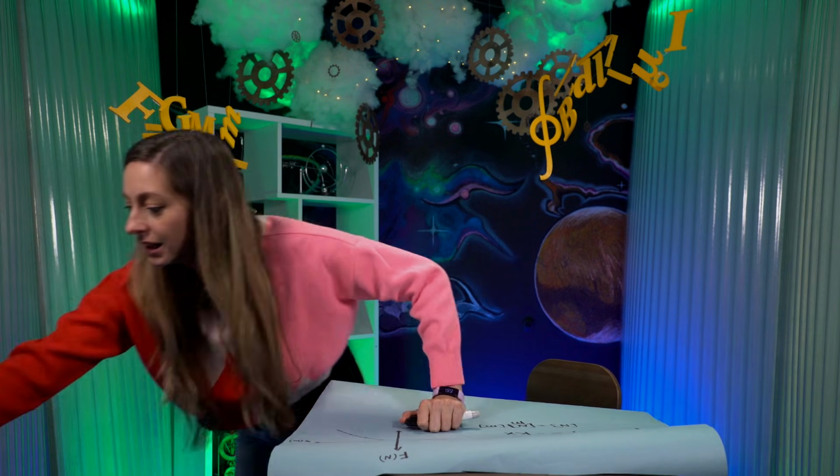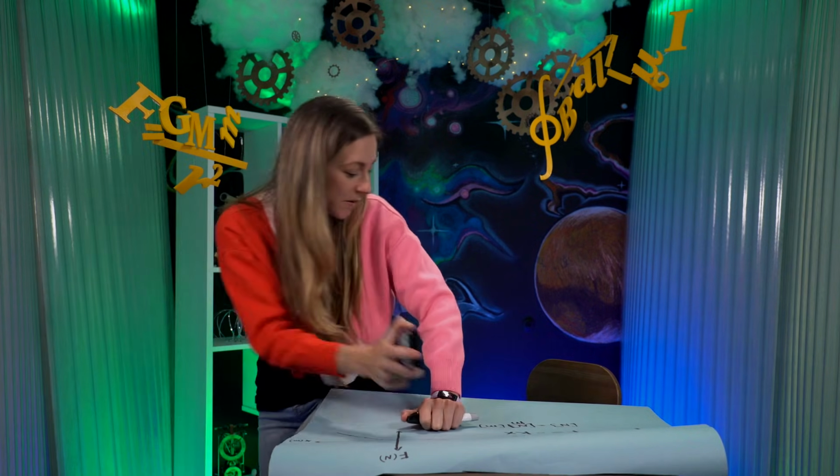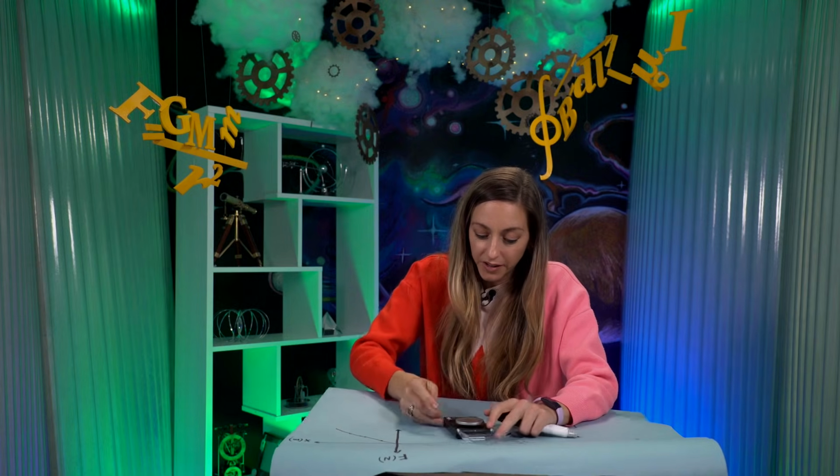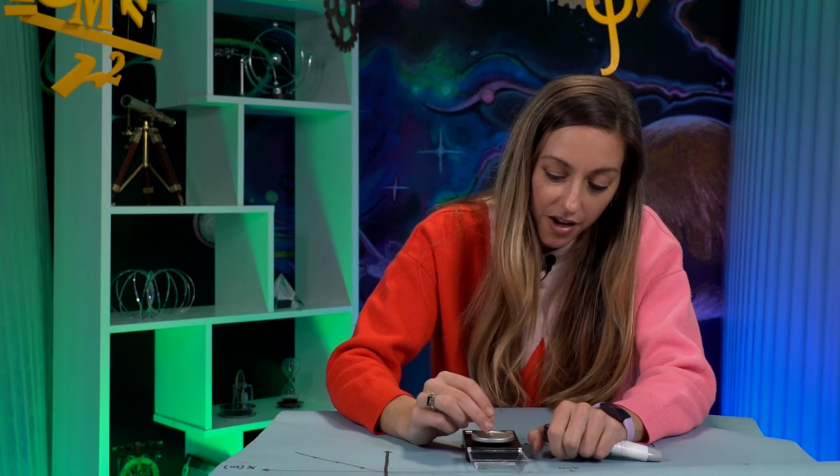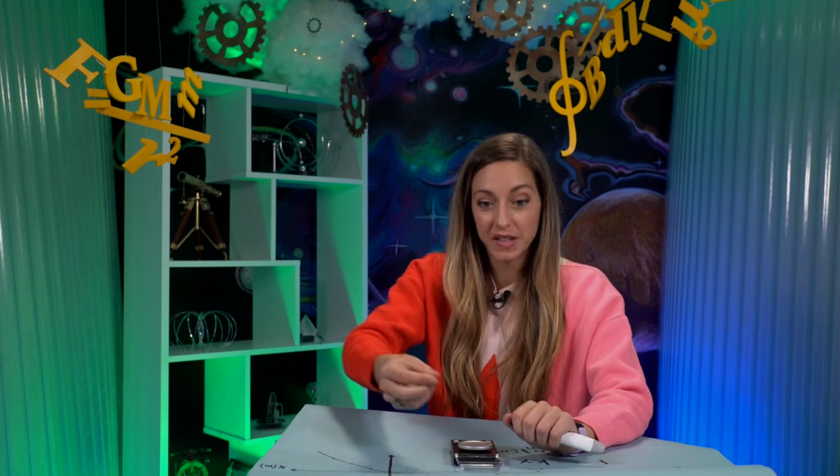Different springs have different spring constants depending on the size, composition, construction. So I measured this spring earlier from a clicky pen. And I measured on the scale. So I pressed it down until it maxed out at 2 ounces, which is 0.55 newtons, and I divided that by the displacement, and it only displaced about 2 millimeters, which is 0.002 meters.